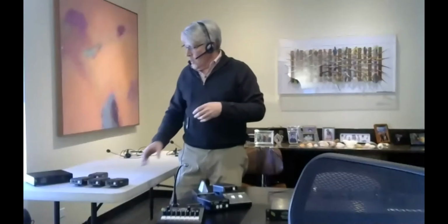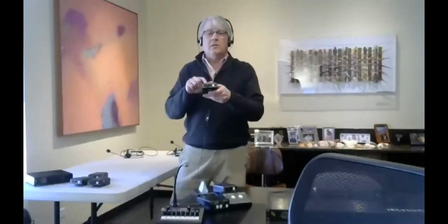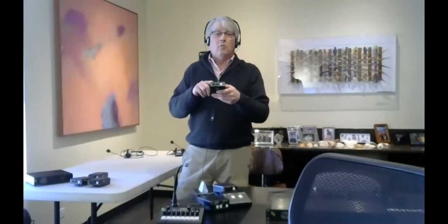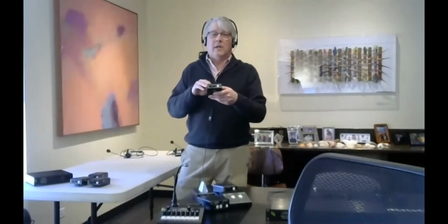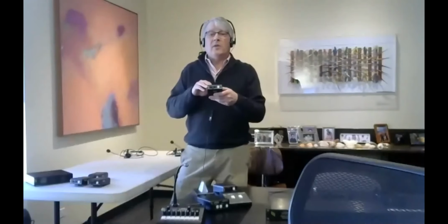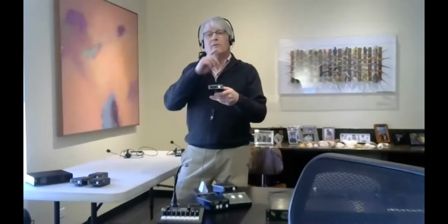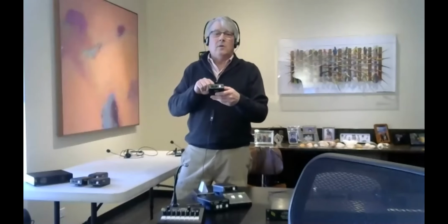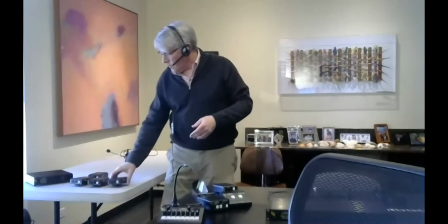Okay, so we have side tone built into this unit that you can configure so that you hear yourself, but it doesn't come back from this mix-minus circuit. So you hear yourself nice and clear, right in time, because in the digital world, there's always time delay. There's always latency. It's very small, but it can bother people if you hear yourself talk and it takes time to come back to you. Local side tone, you're going to hear immediately. So that's some of the background.